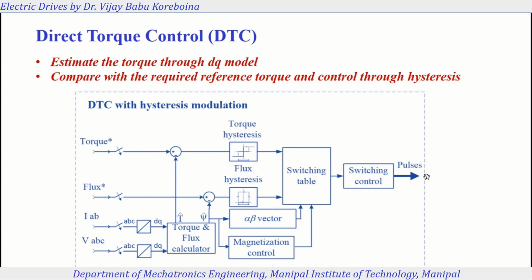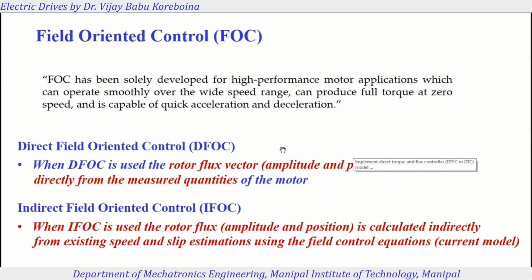So that is direct torque control. Now, any guess of what sort of problems might be here? Since we are using the torque hysteresis band control, it will have fixed ripple. And the frequencies also will be variable frequency, unlike our fixed-frequency PWM pulses. Right? Those are the drawbacks of that.